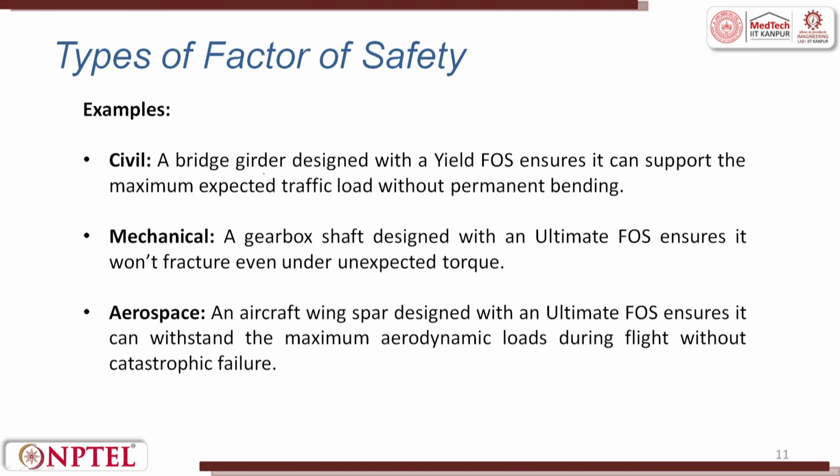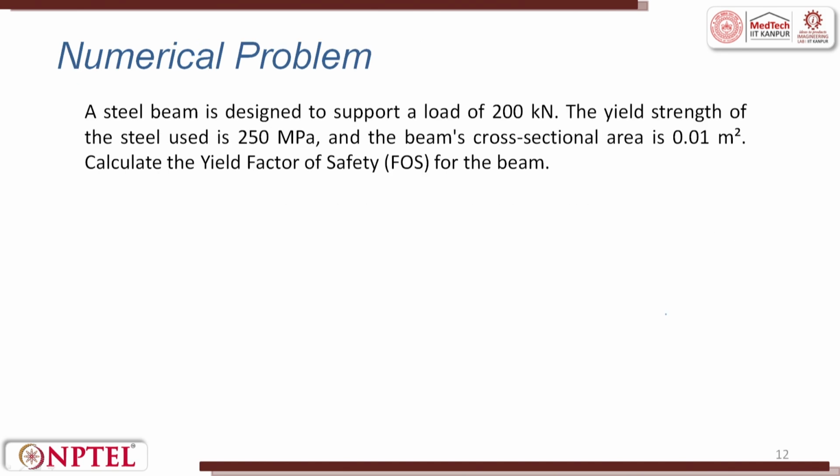A bridge girder designed with yield FOS ensures it can support the maximum expected traffic load without permanent bending. A gearbox shaft designed with an ultimate FOS ensures it won't fracture even under unexpected torque conditions. In aerospace, an aircraft wing spar designed with an ultimate FOS ensures it can withstand maximum aerodynamic load during flight without catastrophic failure. Now, let us try to solve a problem.